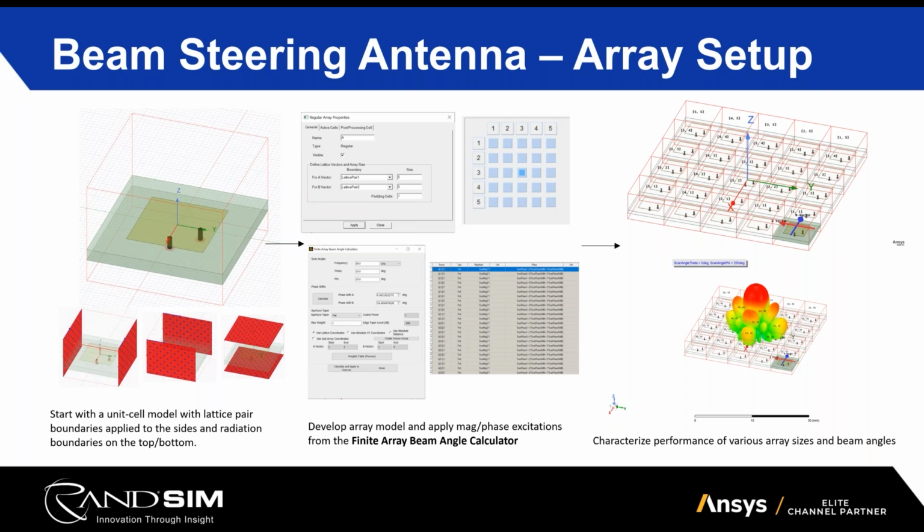And then once we want to steer it, we can utilize our finite array beam angle calculator, where we specify a theta and phi angle, and that would then auto propagate into our excitation sources.